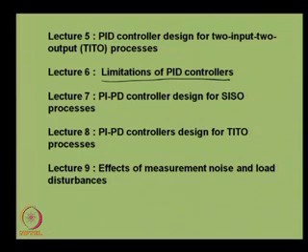Lecture 7 introduces another form of PID controller often known as PIPD controller, where the PI controller will be in series with the plant in the feed forward path, whereas the PD controller will be in the feedback path.